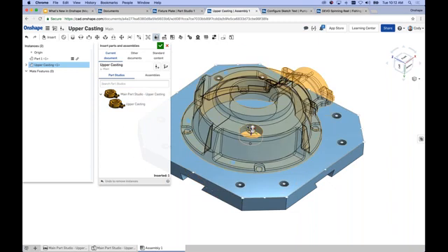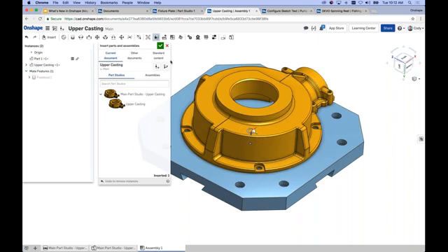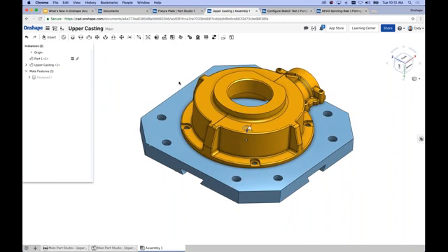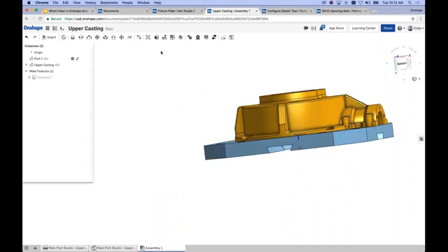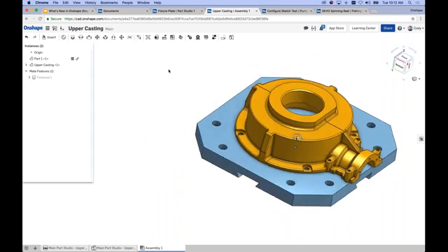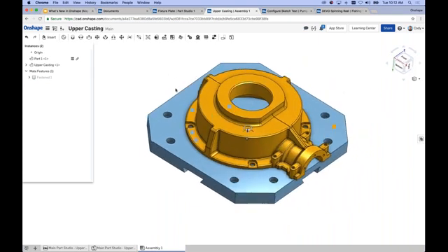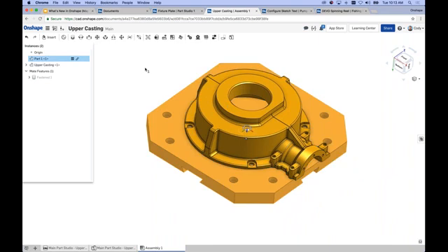Now a tip: you saw I turned on snap mode. If you turn on snap mode, it will automatically look for any existing mate connectors in the part and start to attach them to the geometry. So in this case, I've inserted it and made it into place with that single click. You can see the fastened mate there. That's the benefit I get from adding that explicit mate connector in the Part Studio: I can insert it on the fly using snap mode. Kind of an aside there, but worth mentioning. Cool tip.